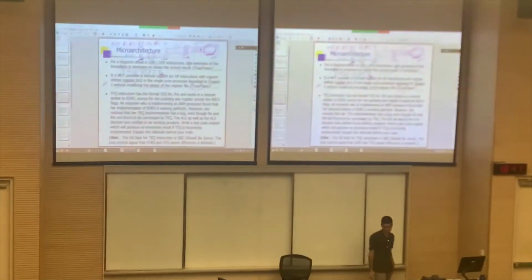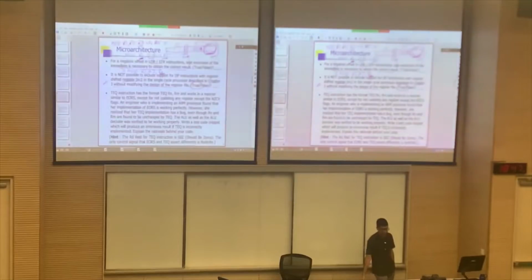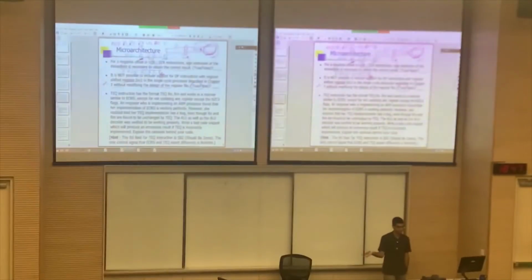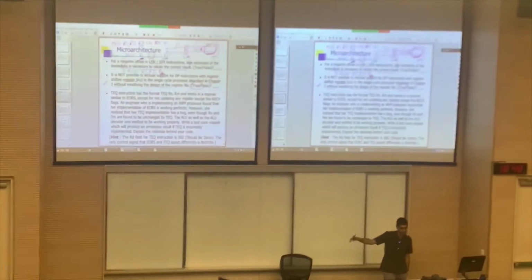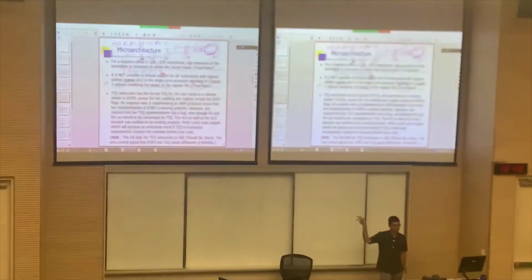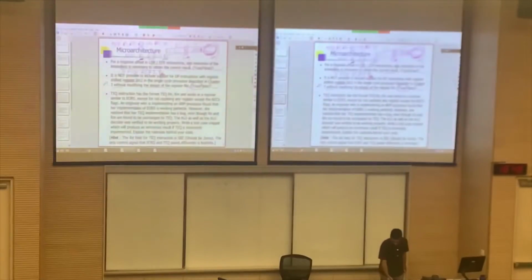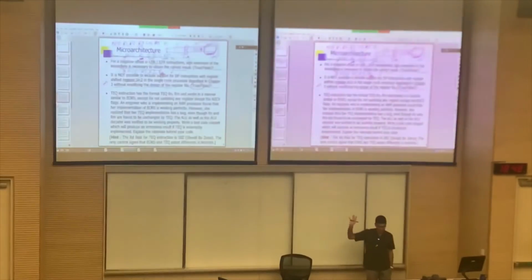So registers are just an abstraction rather than something physical. That's a story that we learned through register renaming. So here, in some sense, it's an internal renaming that is done. Okay, not to improve performance, but for being able to execute these two as two separate instructions over 2 cycles, which allows us to retain the register file design as such.